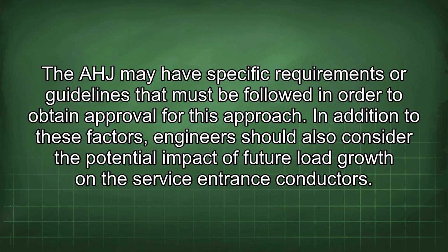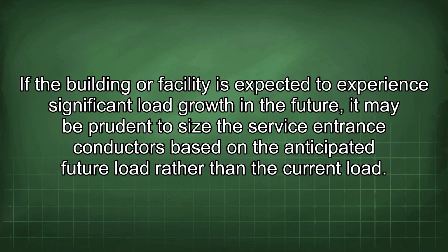In addition to these factors, engineers should also consider the potential impact of future load growth on the service entrance conductors. If the building or facility is expected to experience significant load growth in the future, it may be prudent to size the service entrance conductors based on the anticipated future load rather than the current load.